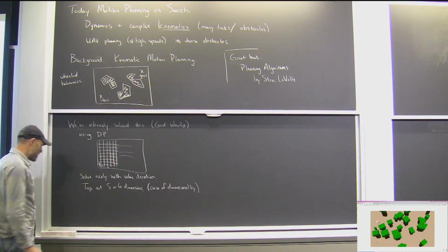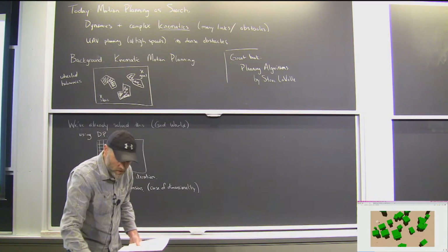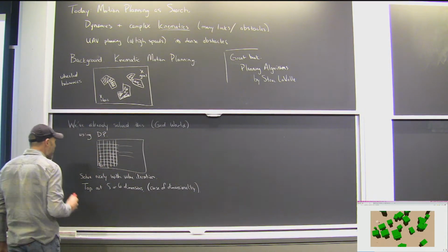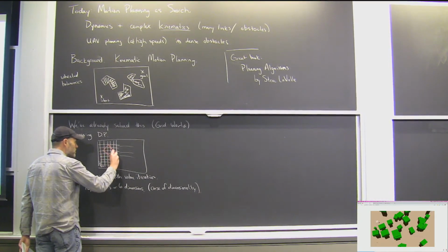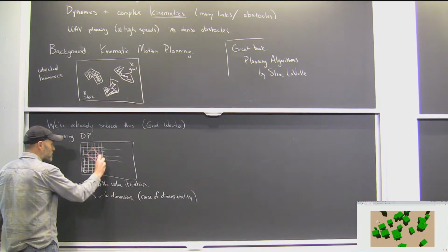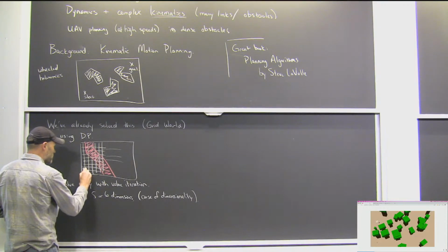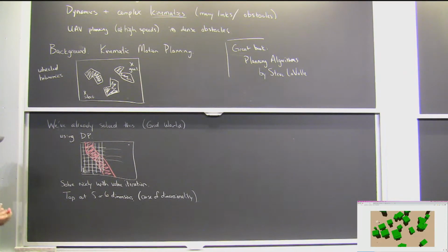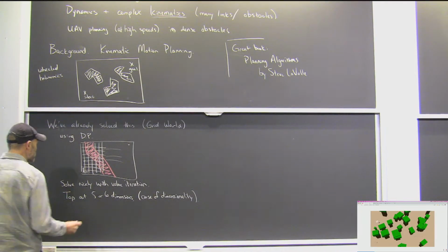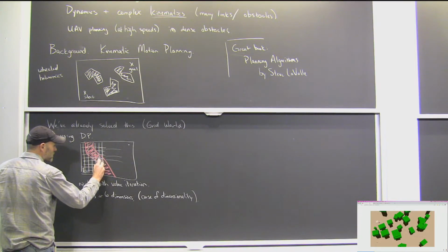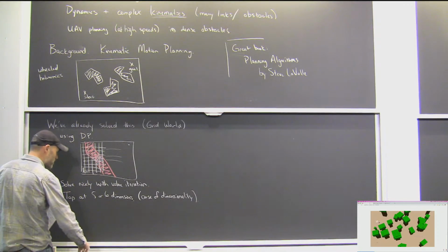But more subtle, and a bigger concern for today, would be that if you took this sort of finite discretization approach, it's not obvious that you have a sound algorithm, in the sense that I could imagine making obstacle courses, right, for which there is a path from the start to the goal, but if I just make a finite discretization, a sort of mesh-based discretization, I might label all of these cells as being in collision and therefore maybe not passable, even though there is actually a path that goes through that corridor.